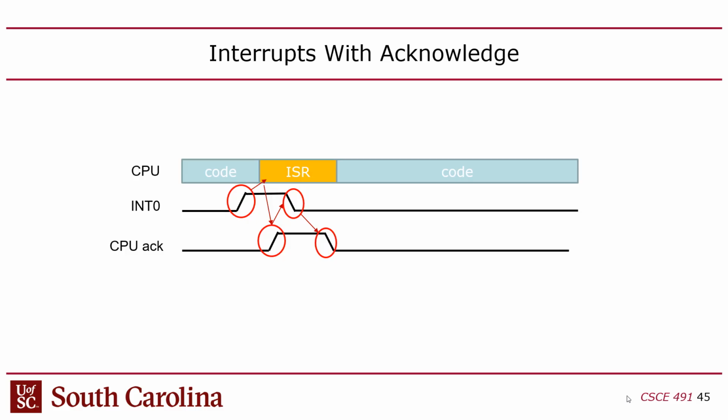It was the one that was on the original Arduino Uno. That chip did not have an acknowledgement system, so it suffered from the problems that you have when you have no acknowledgement, when you just have a one-way interrupt signal, right? The ESP32, I assume it has an acknowledgement system, but I don't even know that for sure. I know that the Nios processor that we use in 313 uses an acknowledgement-based approach. You guys with me? The point is that the way the interrupts work depends on the processor. This is not something that's standardized across every processor type.